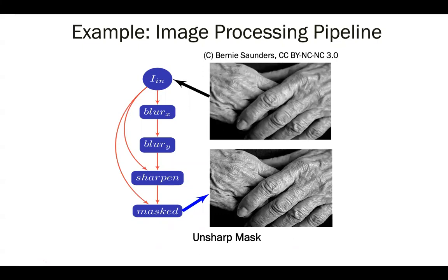Great. So in terms of the coding logic, the architectural approach is the same. It's a combination of streaming and data flow. Each of blurx, blurY, sharpen, and mask is a data flow stage, and they are all connected to each other via FIFOs. Whenever any of these stages has enough input on its FIFOs, it will fire and do the necessary computation.